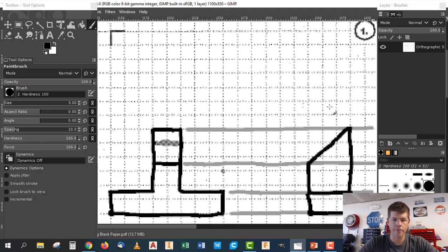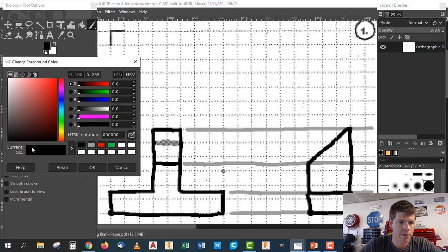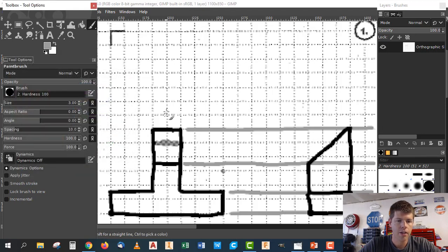Now we're going to look at the top view, and I'm going to go back to projecting lines. So I'm going to switch back to my gray color. If you're using a pencil, you can leave these on your drawing. Just do a really light guide line, and then you leave them on there when you're done. So I'm going to come straight. Let's try that again. We can do better than that. Let's come straight down here.